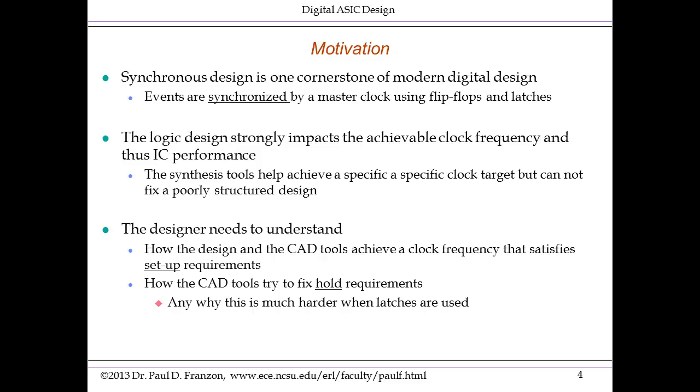Now, getting into it, leading into more detailed motivation of why we're doing this section. You're most probably familiar with the concept of synchronized design. This is a cornerstone, a critical aspect of most modern digital designs. Yes, there is the concept of asynchronous design out there, but it's rarely used today, largely because the CAD tools don't support it well. The central concept in synchronous design is a master clock is distributed to everywhere at the same time, and events are synchronized by this master clock using flip-flops and latches.